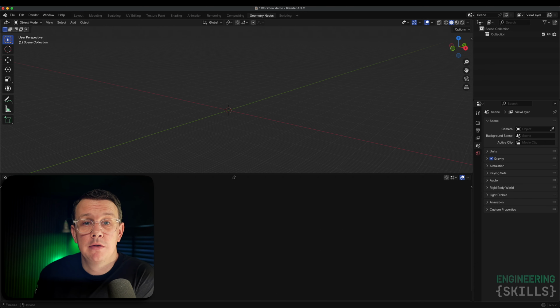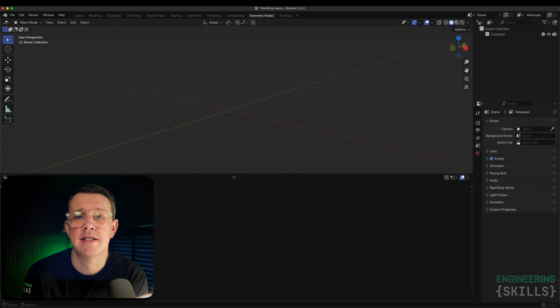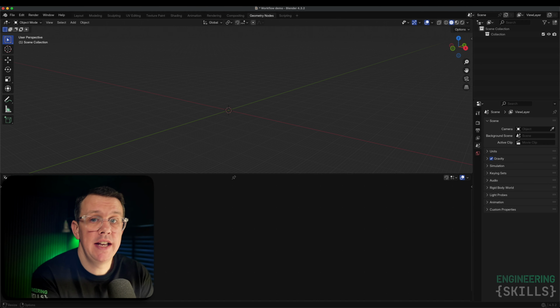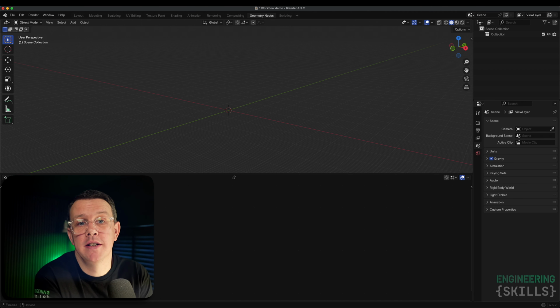Okay, so now that we can perform a 3D truss analysis, the next thing that we might want to do is generate some really interesting geometry. And of course, this is where Blender really shines, because that's what it excels at, generating geometry. One of Blender's great strengths is its modeling tools, and within its modeling tools, in particular, geometry nodes is a really bright light, I suppose you'd say. So now what we'll do is focus on using geometry nodes to generate structural geometries. We can use geometry nodes to parametrically model different geometries, and then essentially bake that geometry and use it as a basis for a structural analysis.